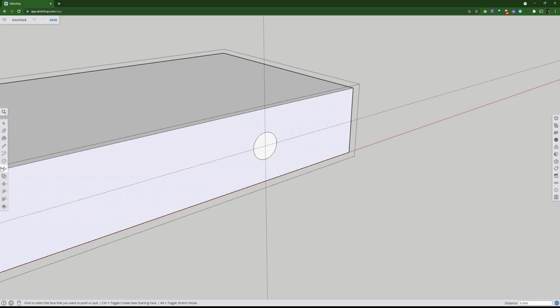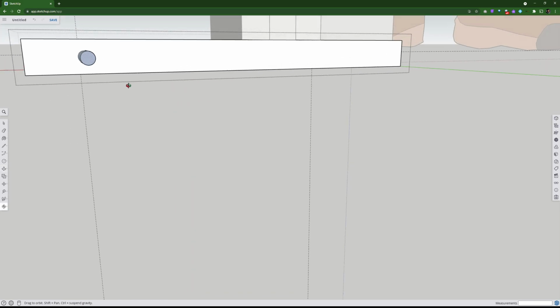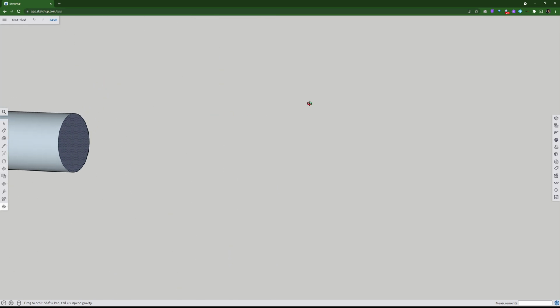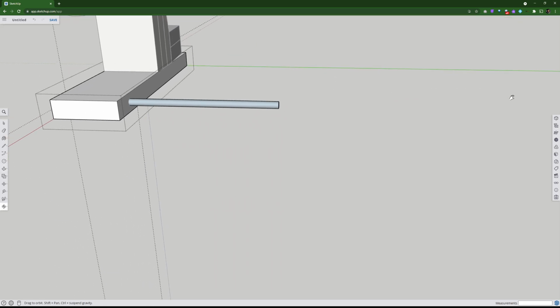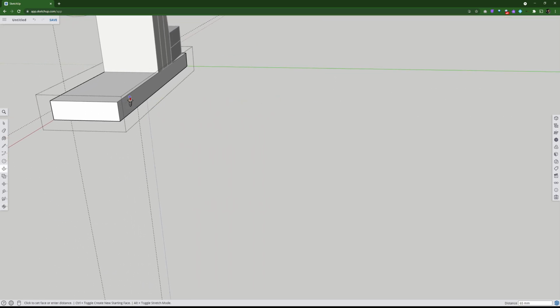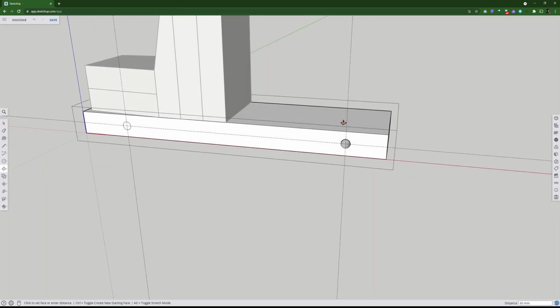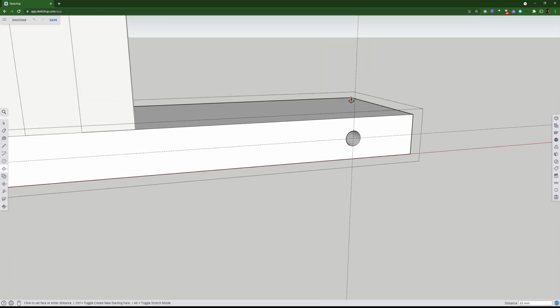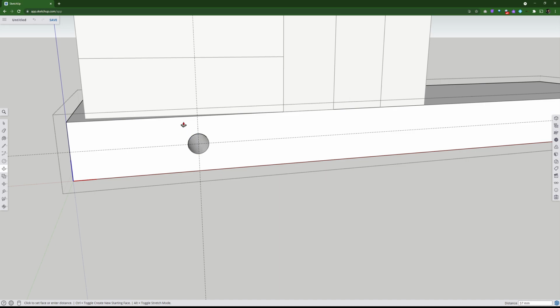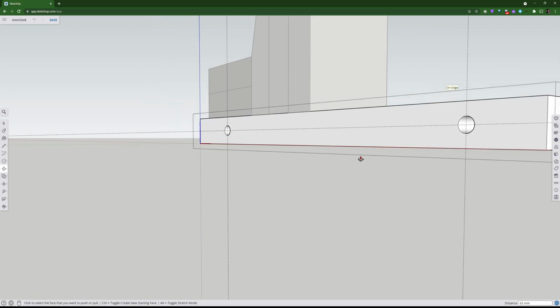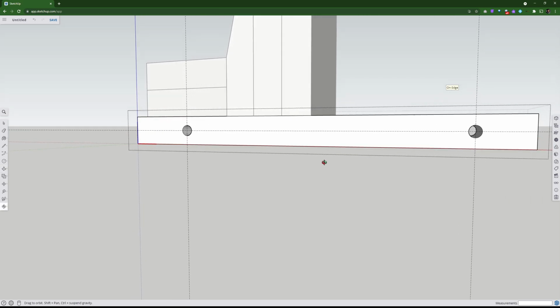Okay, now I'm going to cut a hole. So I went to push, pull, and instead of pulling it out, I'm going to push it in. Now, you could orbit around here, and you could pick that face, and that would do it. Or you could stay where you are, and you could go, well, obviously that corner is the far side. Just click on that. Or if I can't see it, maybe the edge. And let's have a look. Yep, I've drilled all the way through my base.